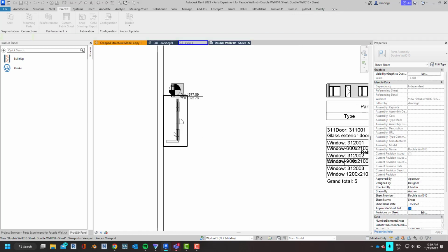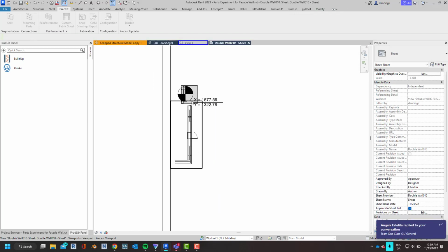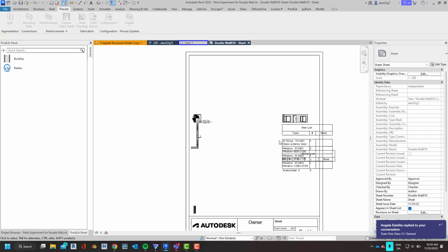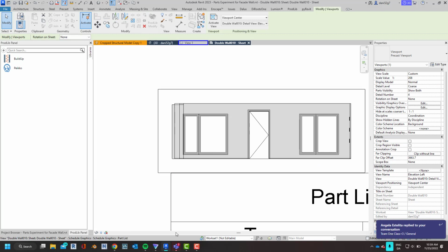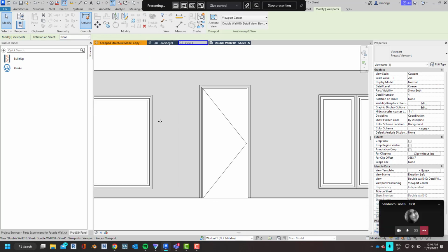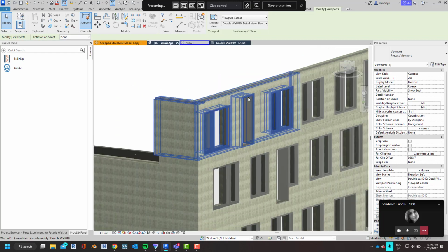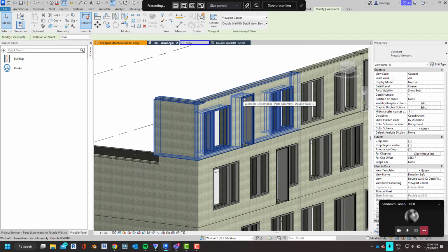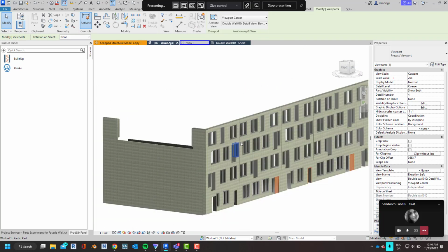You can see here, by the end, we have the door and the windows directly built in to our shop drawing assemblies. The wire boxes, the windows, everything is part of the assembly, and I will post all the families and the Dynamo scripts when I post the recording.